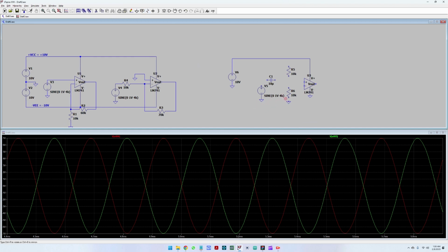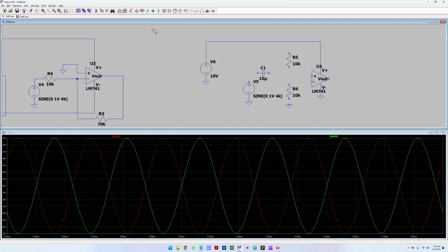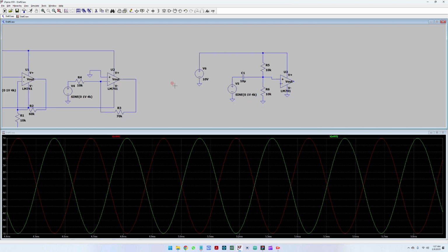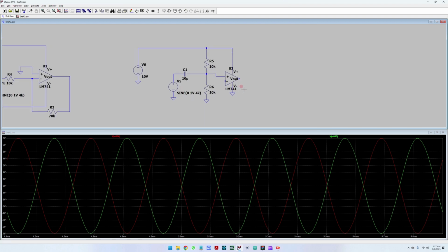More details regarding voltage divider, and also for the capacitor and the resistance at a certain frequency, you can find in the basic electronics capacitor video and basic electronics resistor video. Okay. Now we are just connecting the middle point here, the 5-volt point, to the non-inverting input.